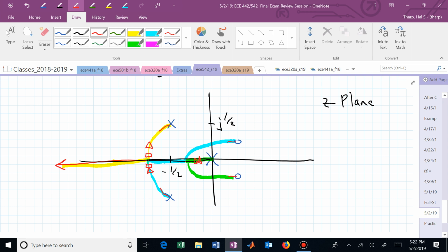What would happen if the earlier picture was true? We didn't have a re-entry, we didn't have a breakaway. So what happens on the negative real axis as we look at K? We just have a monotonically increasing K. So now if you sketched K as a value from 0 to -2, and it was monotonic, you would say, oh, I had my earlier root locus pattern. If you sketched K from 0 to -2 and it had a relative max and then a relative min and then it starts getting big, oh, I must have a breakaway and a re-entry between 0 and -2. That might be easier than the phase angle condition, because the K formula, you just have to plug in real values of Z and evaluate it.